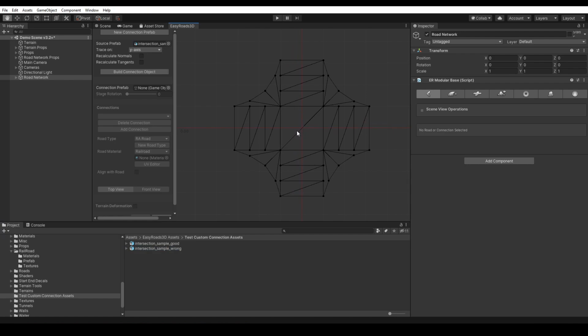The mesh extraction system is pretty robust, but one thing to pay attention to are these dots. They represent extracted mesh edges, edges where roads can connect. These extracted mesh edges can be inside the mesh, but it is good practice to avoid that they connect with the outer edges, because this can potentially result in wrong vertex edge order and issues with terrain deformation and connected roads. Take this model and look at the triangulation. These are dots, extracted edges inside the mesh that connect with the outer dots. You want to avoid this type of triangulation near the outer edges.